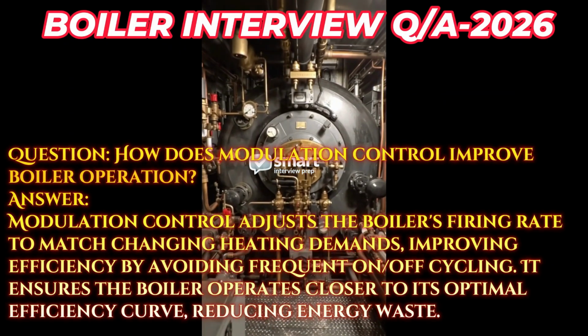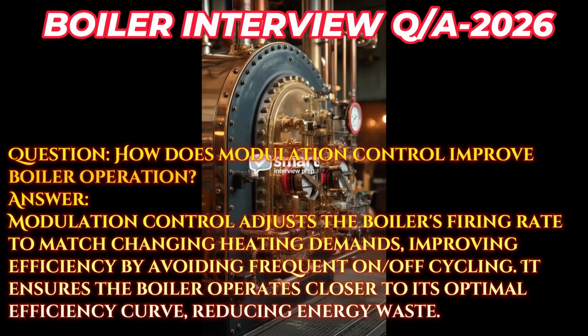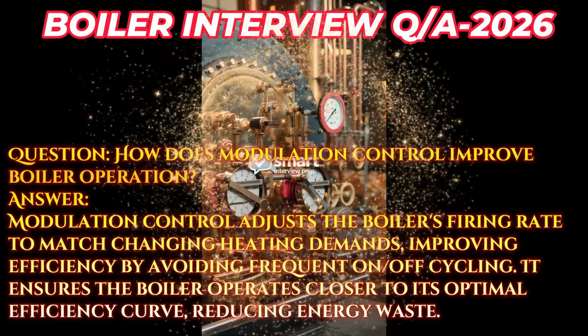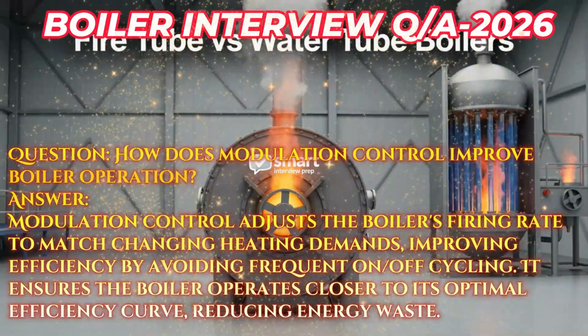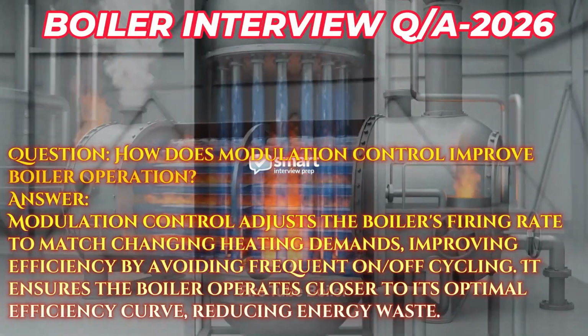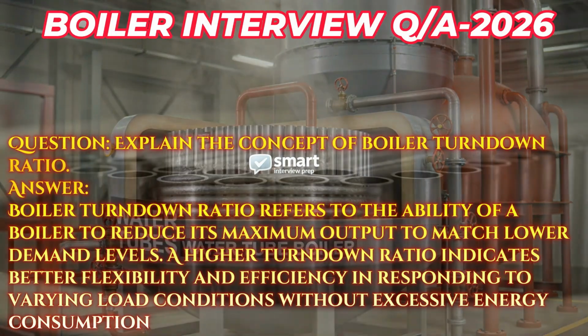Answer. Modulation control adjusts the boiler's firing rate to match changing heating demands, improving efficiency by avoiding frequent on-off cycling. It ensures the boiler operates closer to its optimal efficiency curve, reducing energy waste. Question. Explain the concept of boiler turndown ratio.